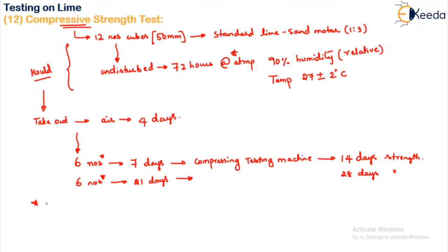Again here we have to uniformly or steadily increase the load. So we have to start at 0 and increase it at a rate of 150 Newton per minute.